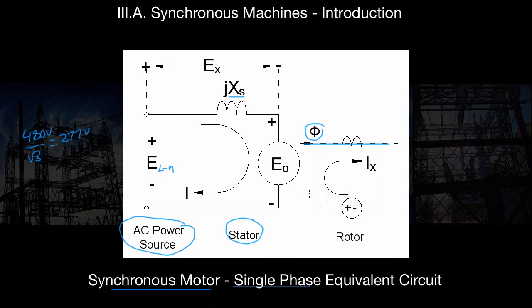So pretty much what they usually do is apply a voltage source on the stator, which creates a rotating magnetic field in that stator. If we were to draw it again, that's our stator, and this is our rotor, and there's a very small air gap in between. This time we're creating that field on the stator, say north, south, north, south. These poles are going to rapidly rotate because it's an alternating current, so the magnetic field is going to rotate as well.